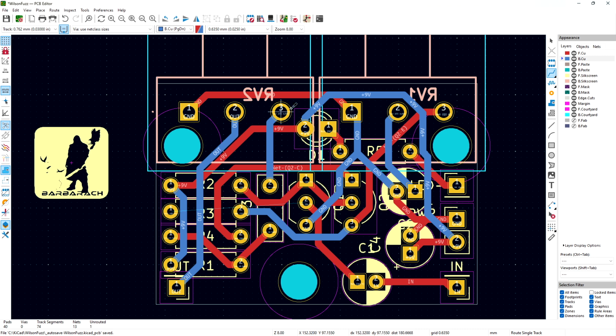So we have to put these pots here because that's the only way they can fit into the pedal. So that's pretty much given. LED, you can play with that. You can put it to the side or in the middle, or you can put it here, but because it has to go out up here, we don't even need to have the LED here. We can wire it directly to the switch. That's also an option.